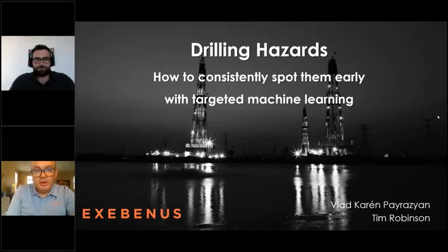This is where most of your non-productive time costs go, and it results mainly from things like differential sticking, which relates to your wellbore stability, your mud cakes, but also mechanical sticking, which is more about dynamic friction related to the movement of the pipes, and hole cleaning issues that result in jammed pipe.